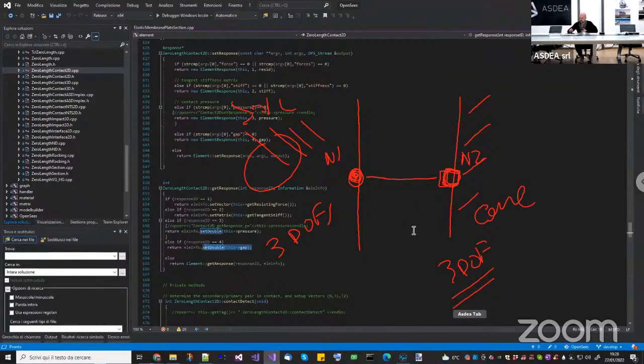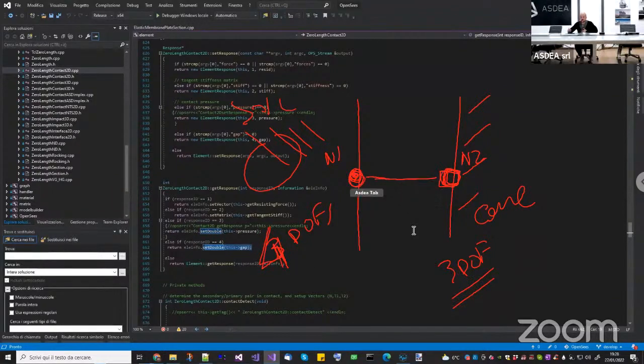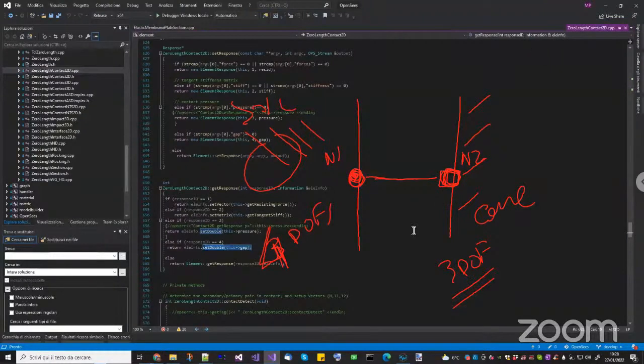Now imagine that for some reason, for concrete you use a 3 DOF standard solid element, but for the soil you use UP elements, so displacement and pressure. Here you have 4 DOFs. Creating a zero length between a 3 DOF and a 4 DOF node is not allowed. What you need is the same number of DOFs.